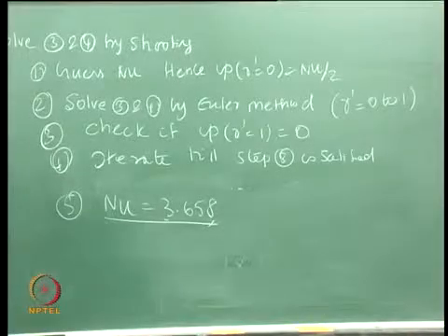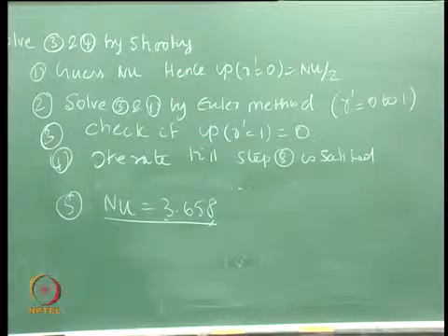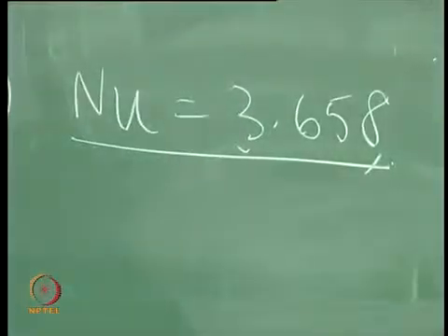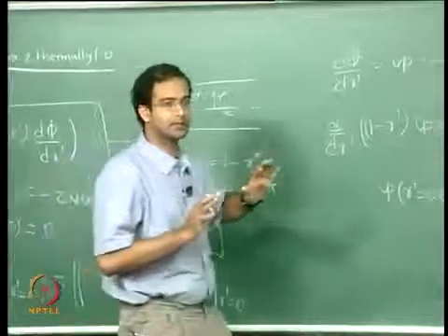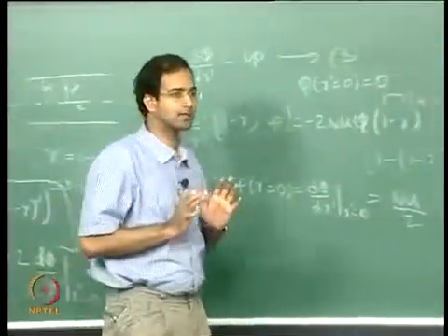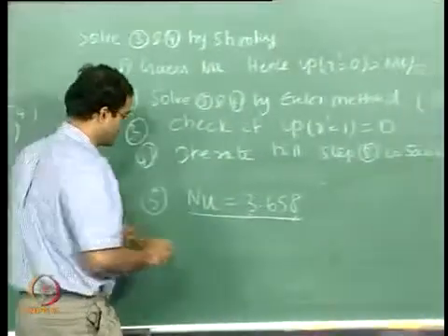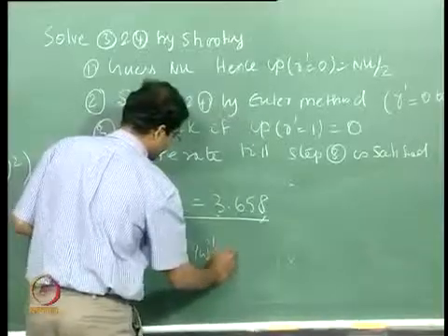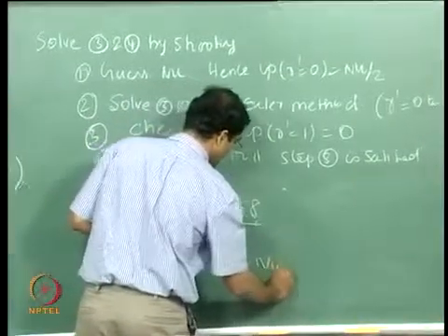Once again, as I said, if you have a thermally and hydrodynamically fully developed case, that is in region 3, you have a constant value, whether it is isothermal or isoflux case. For the isoflux case, what do you remember the value? 4.36.